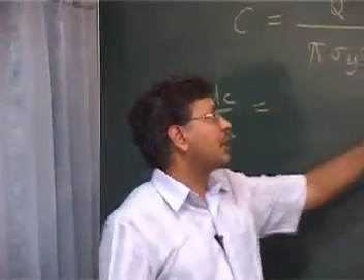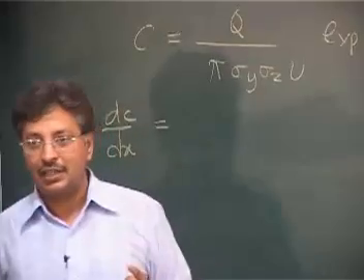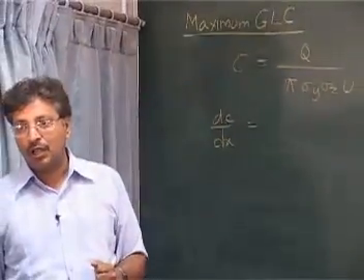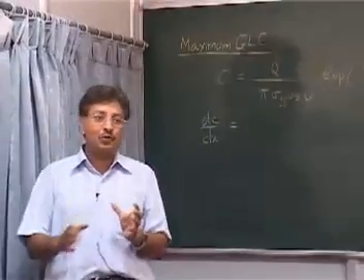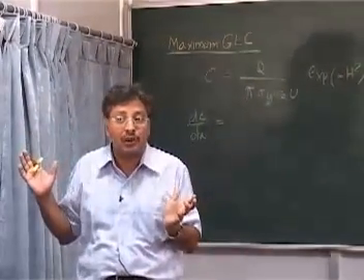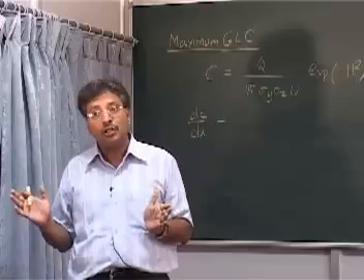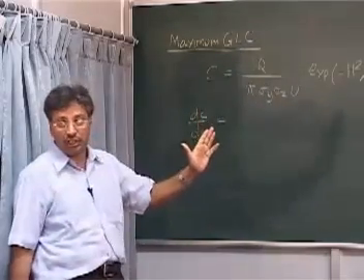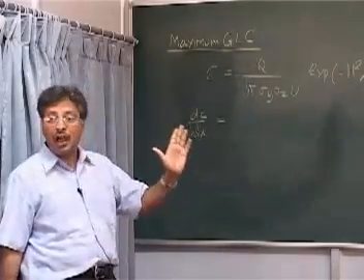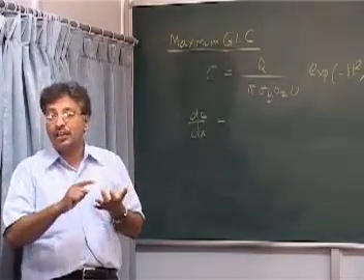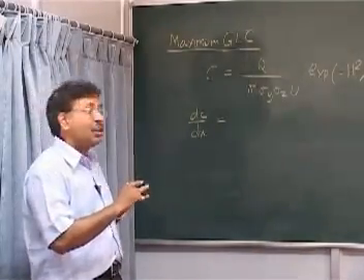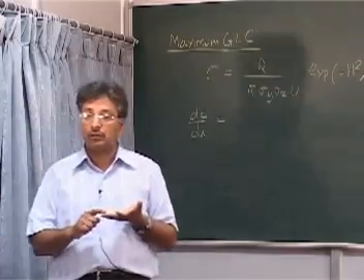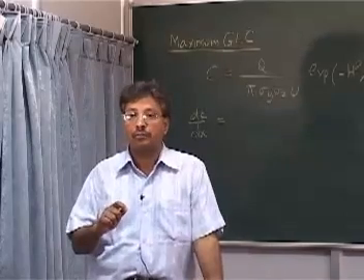What will happen? Say in the first hour the stability was C, then you compute it for C. You can't just work for 1 hour and extrapolate for 24 hours. If you want to compute hourly changing concentration, you have to consider the hourly change in the stability, the hourly change in the wind speed, and the hourly change in the effective height. Nobody can predict what the condition will be 1 hour after this time.